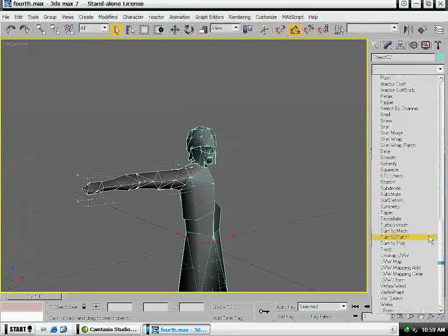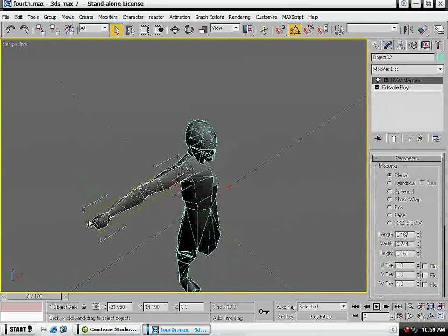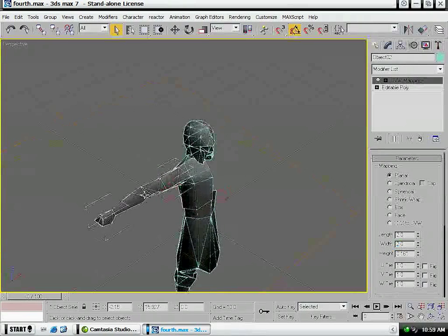you want to apply what's called a UV map. This geometry in 3D space has what's called UV coordinates. But right now, they're probably all messed up since all the cutting, pulling, and extruding we did. So you need to give it new UV coordinates. So you apply a UV map to it. Now the best way, you see right now it sort of forms the geometry. We want to make this square. And to get everything in proportion with each other, we're going to assign all UV maps we use in this project to have a length and width of 2.